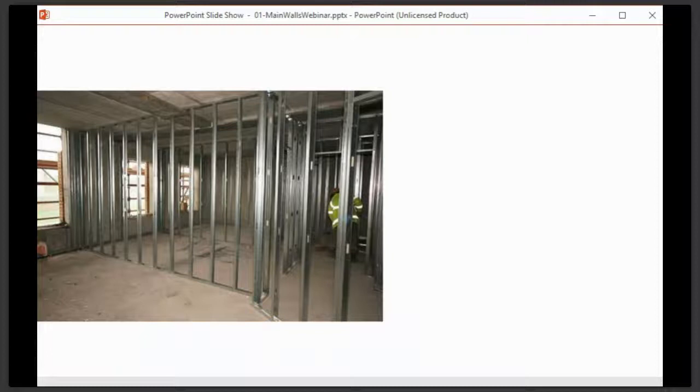The type of wall frame that we looked at there was the timber stud partition, and that's been the most commonly and widely used, certainly in the British Isles and a lot of Europe as well. Something that you'll also see is a metal stud partition. It's exactly the same thing, only it's made with lightweight metal pieces. This is basically a lightweight steel frame. The pieces are cut to size and put into place in exactly the same way. Generally speaking, these started in commercial interiors, where they were used a lot. You don't see them that often in residential interiors, but they are being used. If I'm doing any kind of remodeling or renovation, I've put them in a few times because they're quick and they're easy.